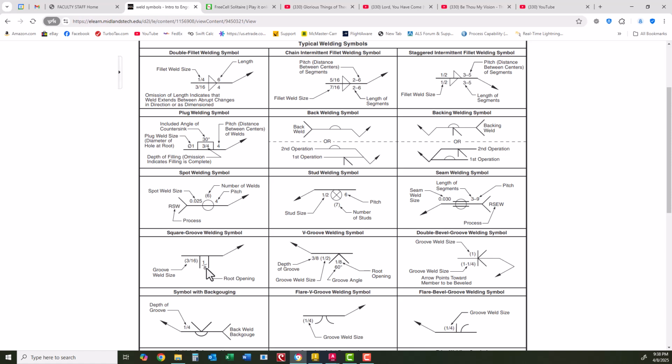And the other thing you want, the welder has to make sure he gets the voltage and the current correct so that he's getting a full melt through to weld without destroying the metal. He wants a full through weld. Otherwise the weld would be only a partial weld and you won't get a very good weld. So you have the square groove weld or butt weld, and then the other one that we're going to be dealing with is